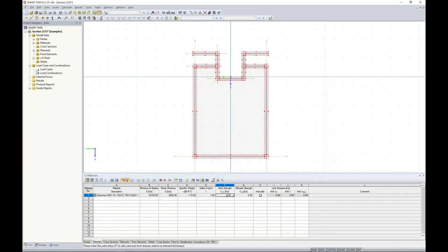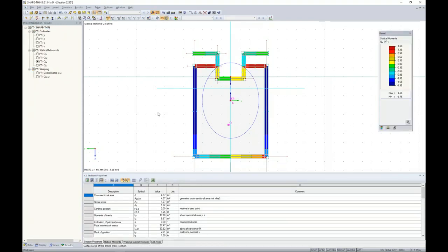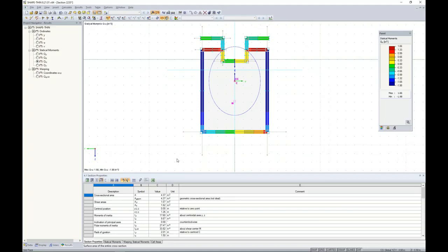Well, the reason for that is because aluminum has different yield strengths depending on if it's for tension, for compression, for shear. So all we need to do is just to set some type of placeholder here. FY equal to 30 is perfectly fine. So that's the reason why the program populates 0 there. So we can rerun our calculation, and now we can see that we are presented with our results.